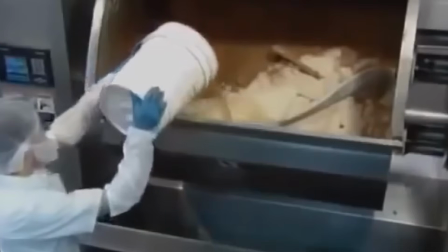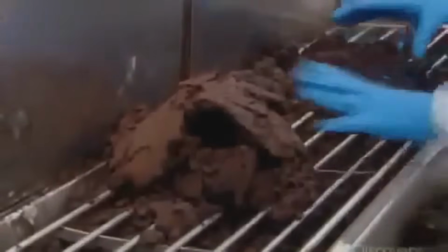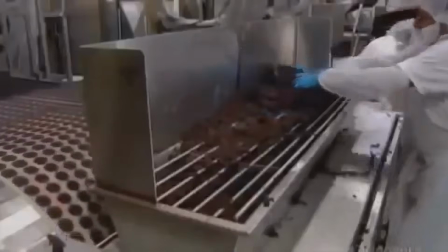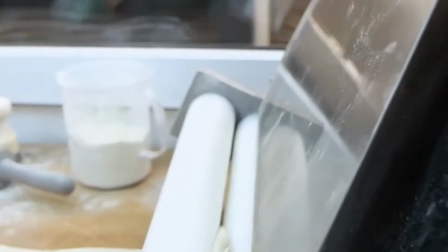Then it's time for the liquid components to enter the system. These include vegetable shortening, often a blend of palm and canola oil, along with a sugar syrup or glucose solution, invert sugar, lecithin, and vanillin or other flavoring agents. The fats and liquids are stored in temperature-controlled tanks and are metered into the mixer through heated pipes. The temperature of the fats is critical. Too cold, and they won't disperse evenly. Too hot, and they could melt too aggressively, breaking down the emulsion and affecting dough integrity.